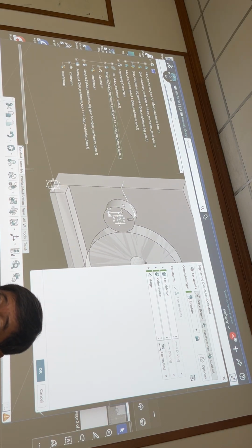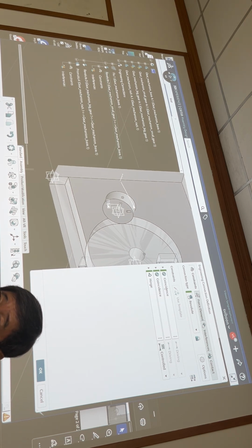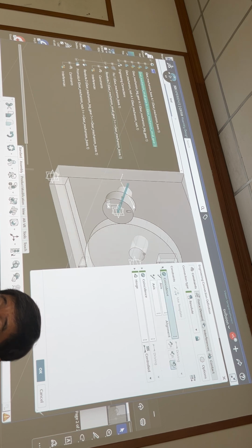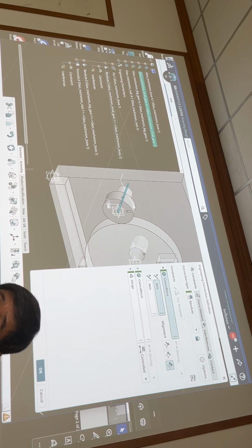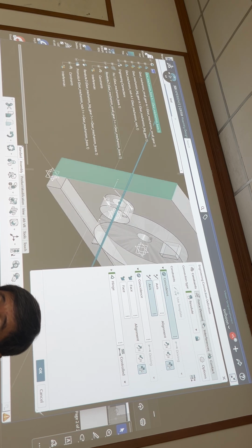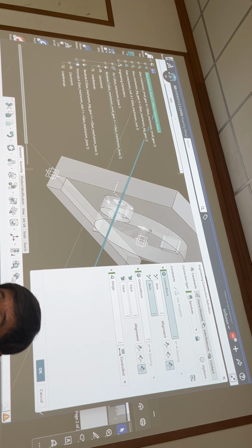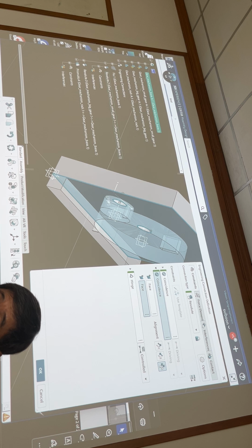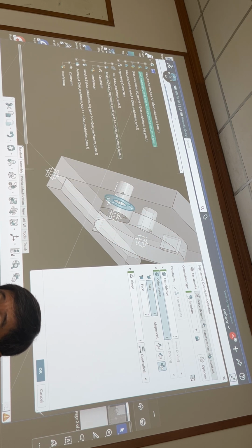You add the revolute joint. The small gear, this one and this one, right. We have this axis and this axis of the holes to be the same, right, same direction. Coincident face of the gear and face of this one have to be the same, right? This one. Right. Hinge.